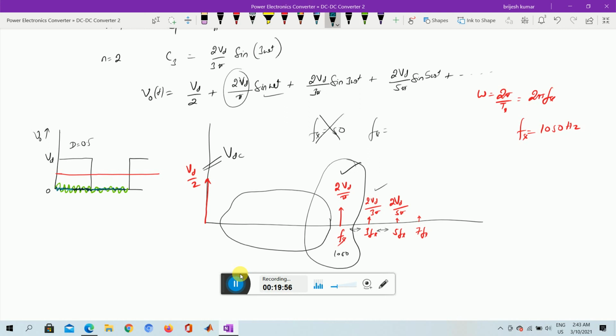If this frequency is 50 Hertz, it is problematic. Then we'll have a cycle like this, and this will be dangerous. So we don't want this 50 Hertz. We want a very small output voltage over here. We want it to be 21 times 50, so this is okay. This is why the switching frequency has to be more than 21 times 50, in that range. And we have to take care of the Fourier series. We understood this.